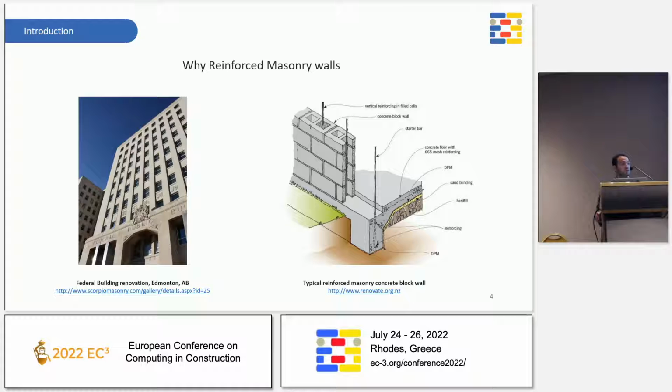During this presentation, we are going to apply the methodology on reinforced masonry walls. Before I start, I'd like to introduce what's meant by reinforced masonry walls. They are concrete blocks with a void inside, with the reinforcement. It acts as a regular concrete wall, but it is composed of blocks made of concrete, and then we put some grout in the blocks to act as an integral wall. That's why its performance is almost like reinforced shear walls, and it's commonly used specifically in Canada and the US in administrative buildings, where they use it as the facades. That's why it's important, as it's the first element subjected to blast loads.